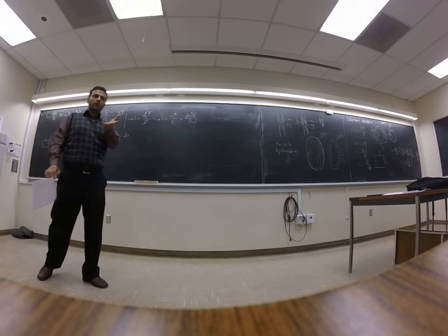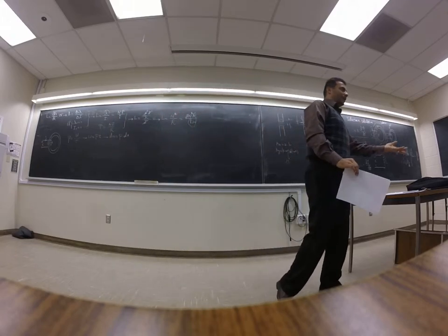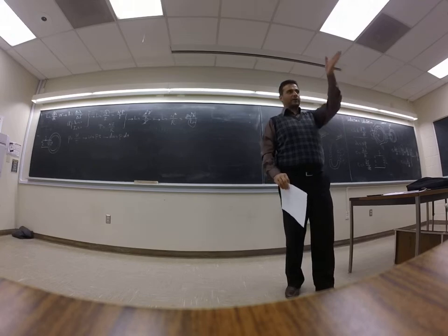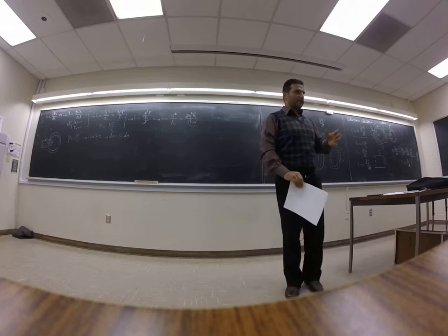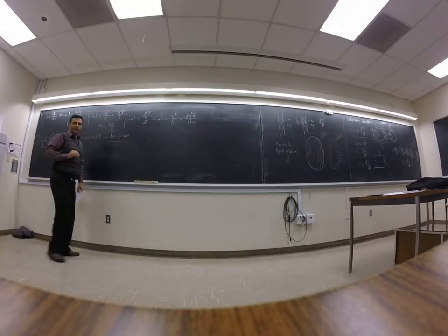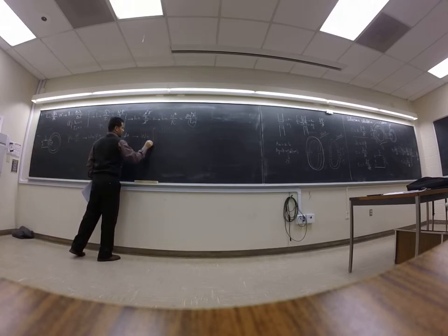You have a refrigerator, a dishwasher, a stove, lights, those kinds of things. These are all power, right? During the day, you can see the power consumption is changing, going up and down, right? So basically, if you want to calculate the energy, you use this equation. You say W is the integral of P dt, right?